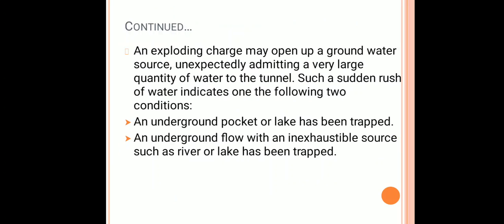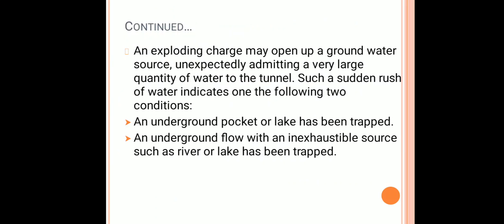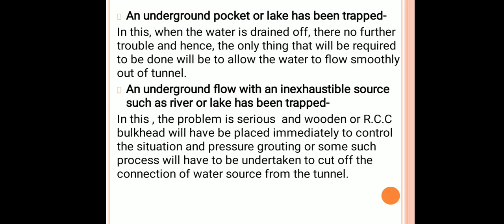Such a sudden rush of water indicates one of two conditions. First, there may be a possibility that an underground pocket or lake has been trapped at the time of tunnel excavation, and the second condition is that an underground flow with an inexhaustible source such as a river or lake has been trapped. Now we will discuss these conditions in detail one by one. The first condition is an underground pocket or lake has been trapped.